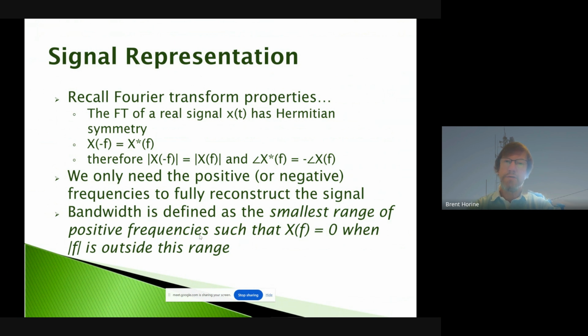But other times, by the time we're transmitting, let's say, we're dealing with real signals, right? And so we take the real part of that and we end up with a cosine. But we have a coefficient out front because that's going to determine the amplitude of our signal. Otherwise, a cosine would give us a peak-to-peak of plus or minus 1 amplitude or volt, let's say, right? And so we might want to scale that to other levels. So we'll have a coefficient out front.